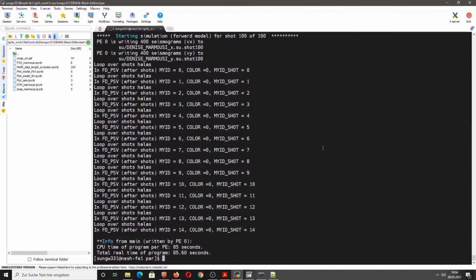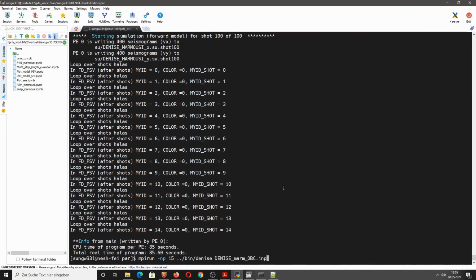So finally, I want to mention another thing. I simply used this mpirun on the login node of the NEC cluster. This has two major disadvantages. First of all, this login node only has 32 cores. So the maximum parallelization that you can use by the domain decomposition is 32 cores, which is not really much actually. So you should use this approach only to test your code, but not actually run the code for 7 days or something like that.